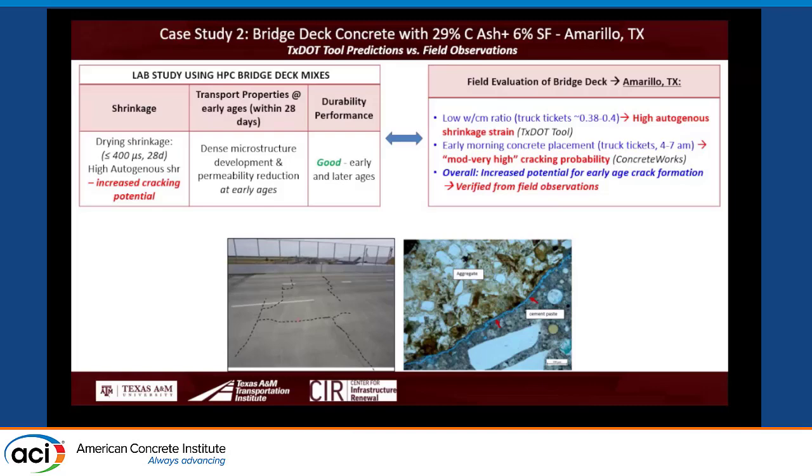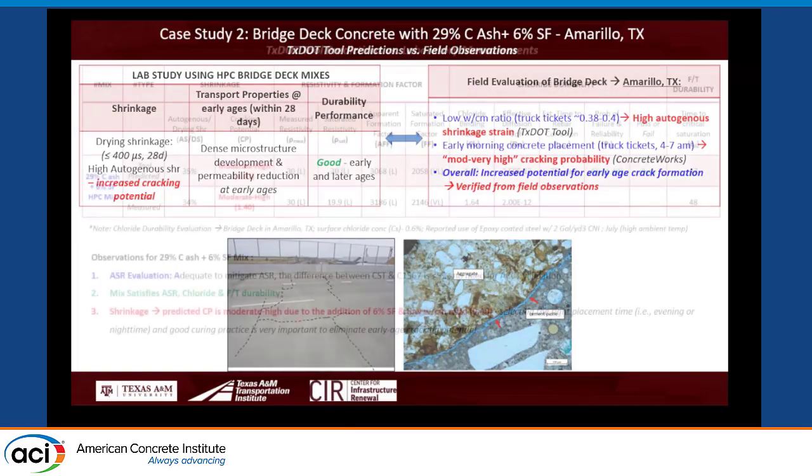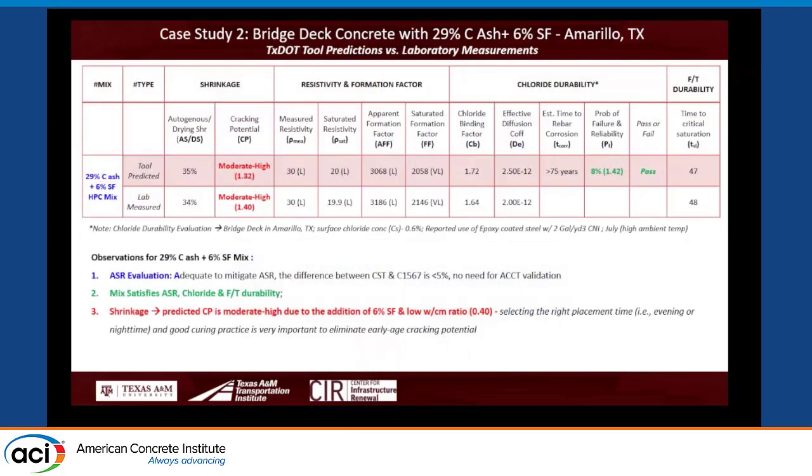Verified by petrographic examination. This is a classical example of why this mix cracks: because of the wrong time of placement. And autogenous shrinkage, TXDOT said, wait a minute, we don't know, but it is important, right? So it very much explains the actual case studies of this approach.